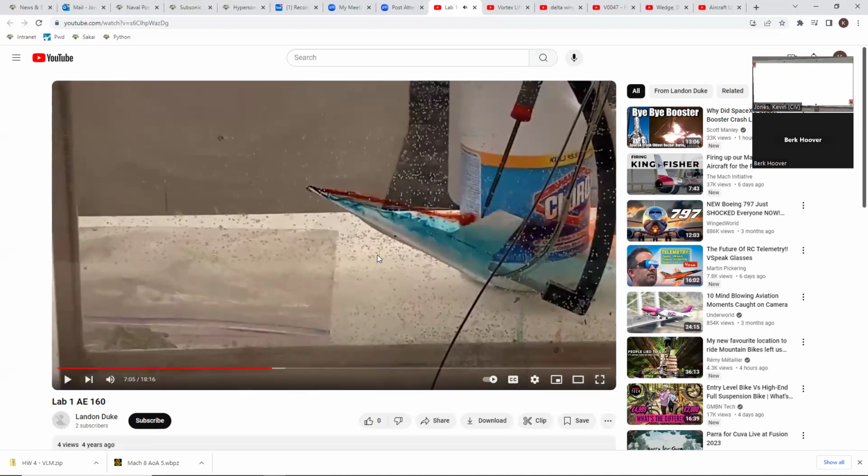This was actually a big problem on the F-18 when it first came out. The original A version, they would get these vortices peeling off of those wings' leading edge extensions. They go forward along the fuselage. And what was happening, the F-18's got the twin vertical fins back here, and the bursting was happening pretty close to the fins, but it could happen asymmetrically. So one side would burst forward, one would burst back. And so it was, I think, doing actual structural damage to the fins. But it also produced asymmetric loads on the vehicle.